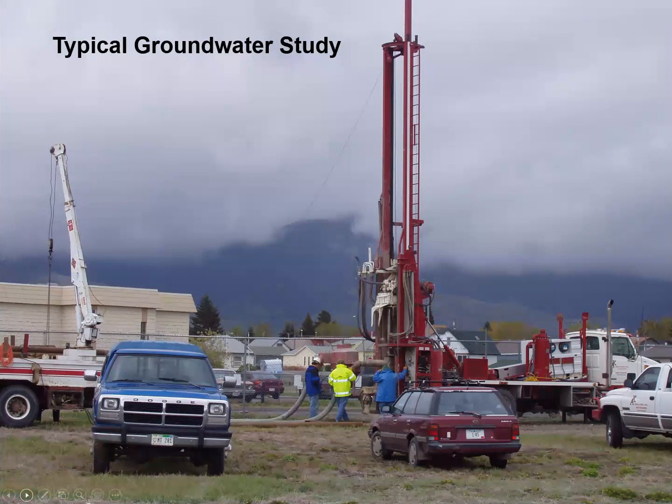So a typical groundwater study is, and in this case, they were drilling with air, but they'll bore a hole, they'll look at what they drill up and start to determine what the hydrostratigraphy is. They'll put in the well, and then they can measure water quality in the aquifer wherever the screen zone is, so at what depth that screen zone is. And then they can also measure water levels.